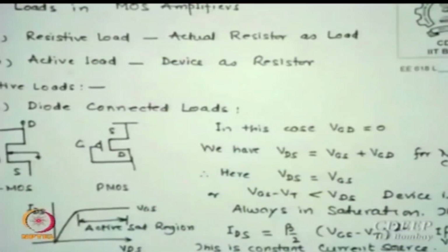And then if you evaluate the resistance seen, you can see from your IDS versus VDS characteristics, if the device remains in saturation throughout, then for a given VGS, which is VDD minus Vs here, because VG is connected to drain, VGS is VDD minus Vs. If that remains always smaller than or equal to VDS, the device will permanently remain in saturation, and then the characteristic shown here has a very large R because the slope is very low. This can act like a resistor.